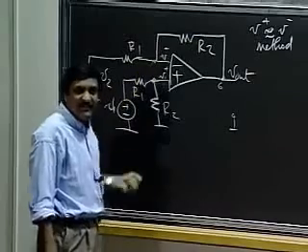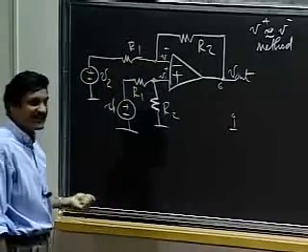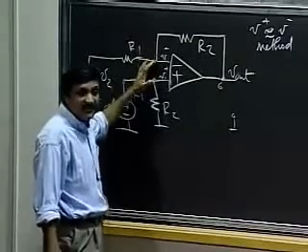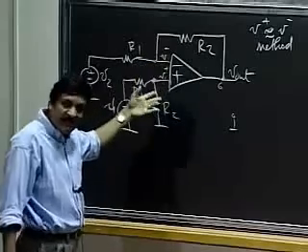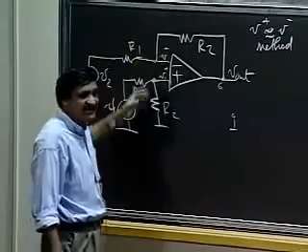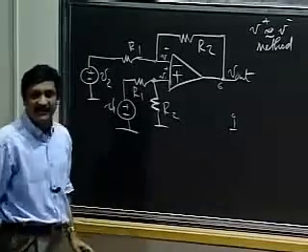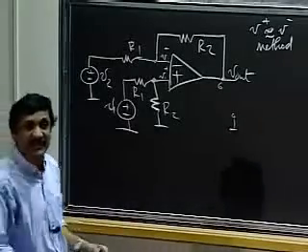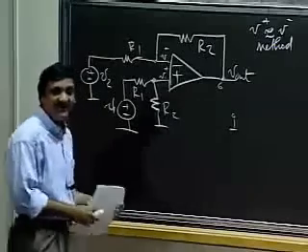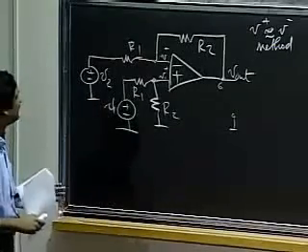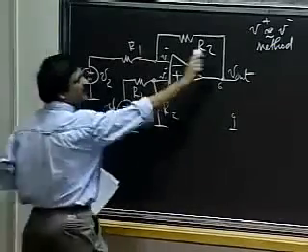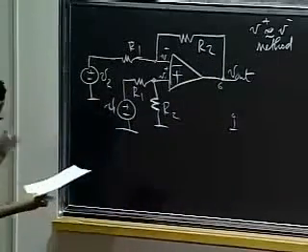This is just a bit of inverted logic: the circuit is going to make that happen, so to analyze the circuit in its steady state, why don't I just go ahead and assume that to begin with? This again goes back to us wanting to be engineers and do whatever's simple, and find the simplest possible way of getting someplace. So I'm going to use the V plus equals V minus method.